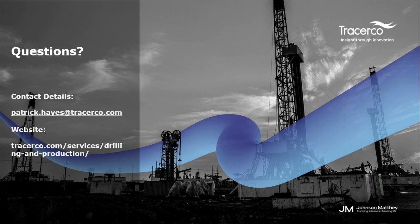But if I know that certain things are going to potentially affect my production behavior, things like choke changes, like bringing on nearby offset wells, I'm going to want to increase my sampling rate to try and capture those changes rather than averaging that out over time. These are all things that really skew your quantification or mask some of the behavior that you're trying to quantify that are big contributions to the error.